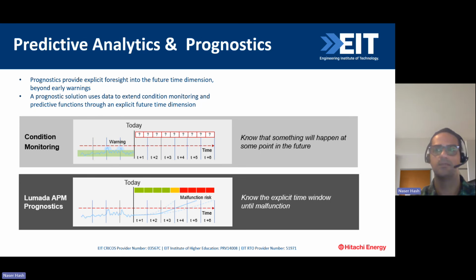The condition monitoring is collecting the data, and that data comes as real-time data. It might be different types of data. It might be electrical data parameters like frequency, voltage, power factor, or it might be mechanical data like vibration, pressure, flow. It comes as real-time data. We're collecting this data, and sometimes we have an expert model to analyze it. For example, if the temperature goes over a certain threshold, there would be an alarm, and then there might be something wrong with the equipment.